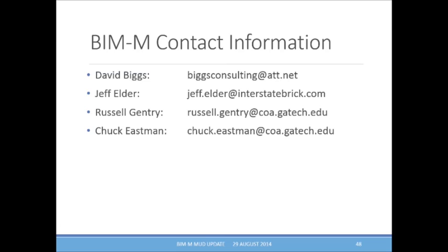Sure. Well, I think that what we do is that we represent not only the material property of the units, but what ASTM standards those units might meet. In terms of code compliance, we're only talking about masonry units here. We're not talking about masonry systems in this project. So the best that we can do for code compliance is to say that this masonry unit meets ASTM C90. So if someone does a search and says, I'm looking for units that meet ASTM C90, then all of those would show up as a query into the database. I don't know if that helps answer the question, but that's the kind of information we're trying to include in the engineering properties section of the database.